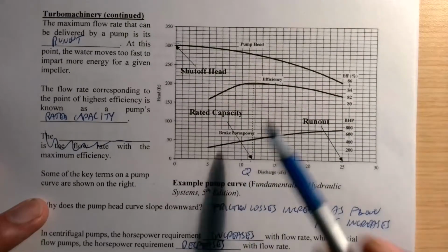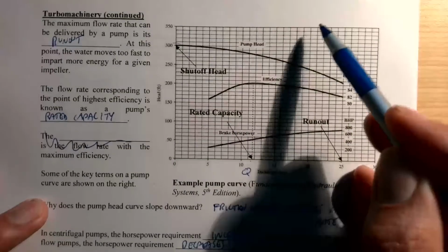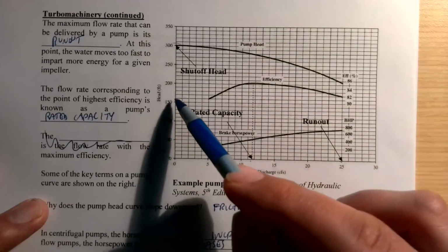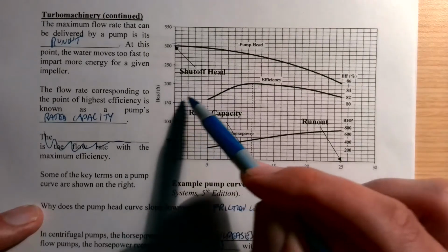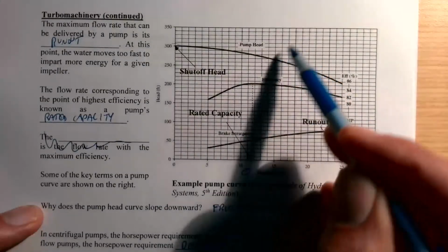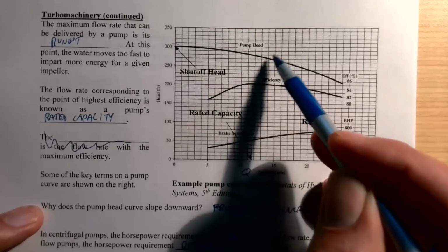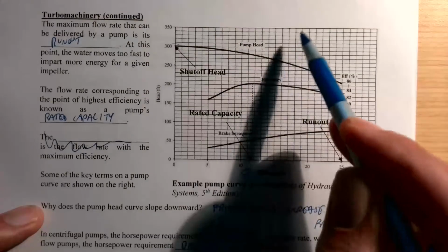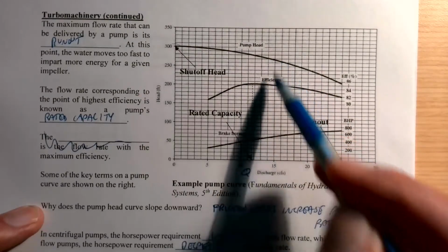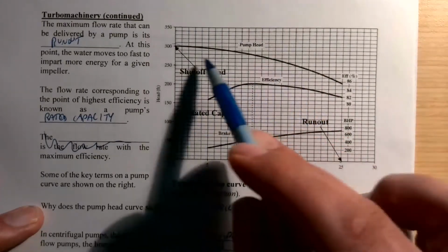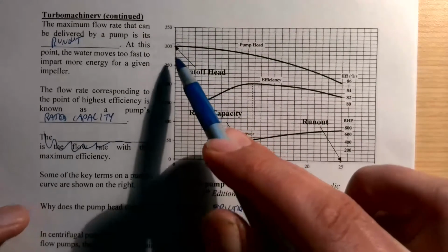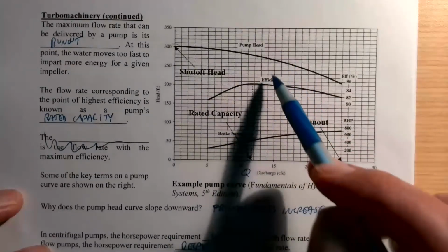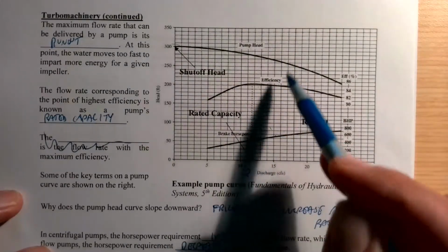So here's Q, and we're going to plot it on here, and it's A plus BQ squared, which means that at Q equals 0, it's going to have some value representing the height that we lift the water, and then the actual energy is going to go up from there as we have more and more friction losses, and then we get less and less energy out of the pump. So wherever those intersect, that's the operating point. That's going to tell us the flow rate down here. That's going to tell us the head that actually gets supplied by the pump and consumed in the pipeline, and then we can read off the efficiency and the power at that flow rate.